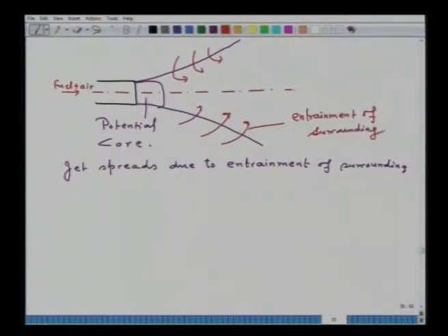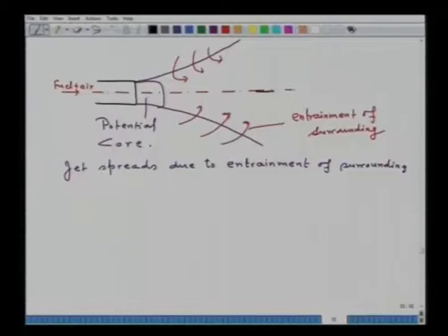So, what we see from this is that when the mixture of fuel and air is discharged through the burner, a free jet is produced. The diameter of the jet increases, and accordingly the velocity of the jet, axially as well as radially, decreases. That is, this is the axial direction and this is the radial direction. Further details of this mixing process for diffusion burner, we will take up next.